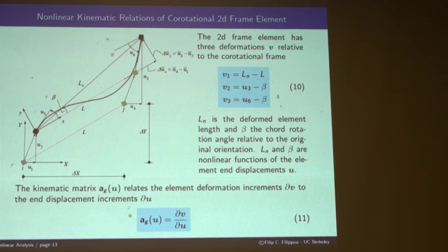With the rotational formulation, of course, the new length is not the same as this one, and consequently, the deformation is there. Now you come along and you say, gee, trained from all these years of p-delta analysis, I'm going to restrain this degree of freedom, and I'm not going to let it come down. Just keep it up. It's supposed to move horizontally, isn't it? You restrain it, boop, tension in the column. What the heck is going on? These OpenSees guys are the biggest loonies ever seen, right? Well, that's truth, that's physics, that's nature. I don't know who the loony is in this case.